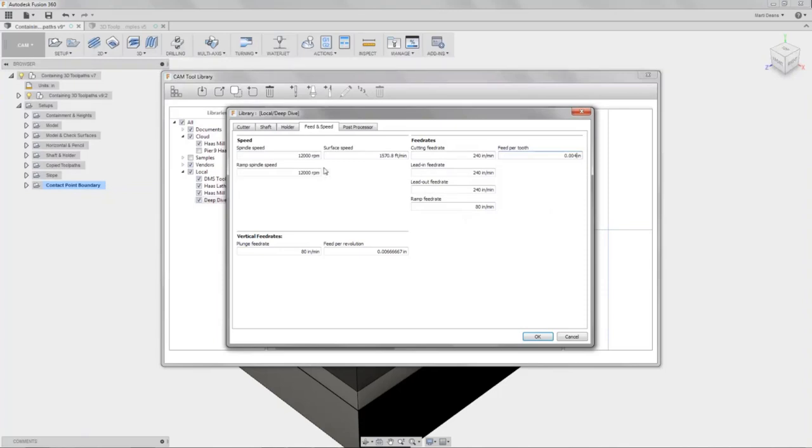And as you guys noticed that I just did, you can either enter a direct spindle speed rate and cutting feed rate. So I could just put in 150, or I can enter the surface speed and feed per tooth values. So these are both calculated using tool parameters like diameter and number of flutes, which is why it's important that those are correct. Otherwise, all these values will be wonky, but I can totally go backward the other way as well. Cool. And then down here I have my vertical feeds, so plunge feed rate and the feed per revolution for plunging.